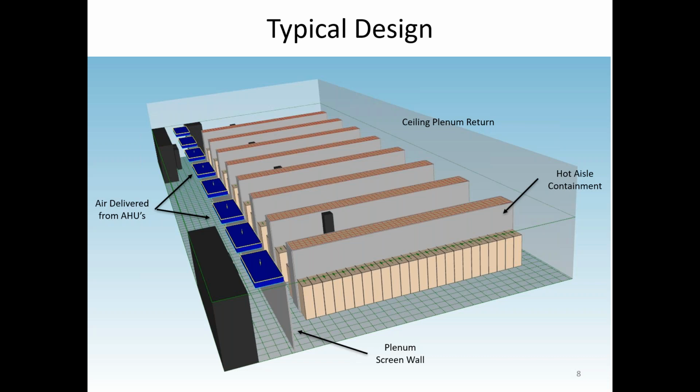I see this one being used quite a bit lately. A lot of the models that come in, a lot of the questions that come in evolve around something along these lines. This is a non-raised floor data center, not my favorite because it's very hard to modulate the air coming in and make sure everybody's happy. Remember, the benefit of a supply plenum is you get to modulate the air using perforated tiles. It is effectively a large duct that you get to basically adjust in any way you want. Here, you don't have that ability. All the air is coming from one side.